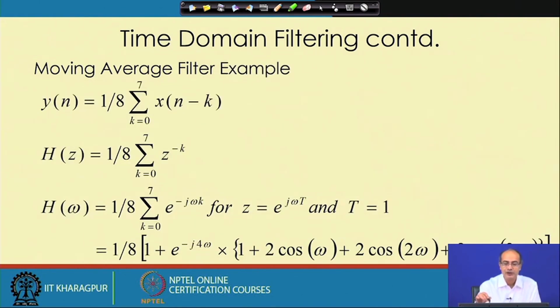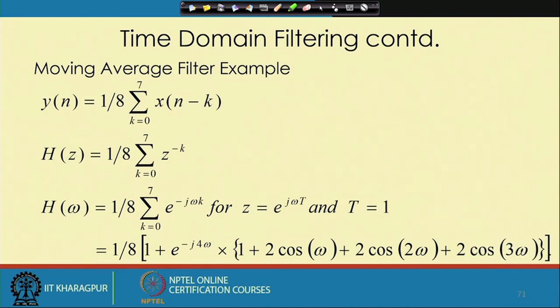So, next we look at one such filter that is taking 8 taps, and here we have taken special care that again it is an integer filter, but it is a uniformly weighted filter. If you look at the tap weights, it would be just like a rectangle.